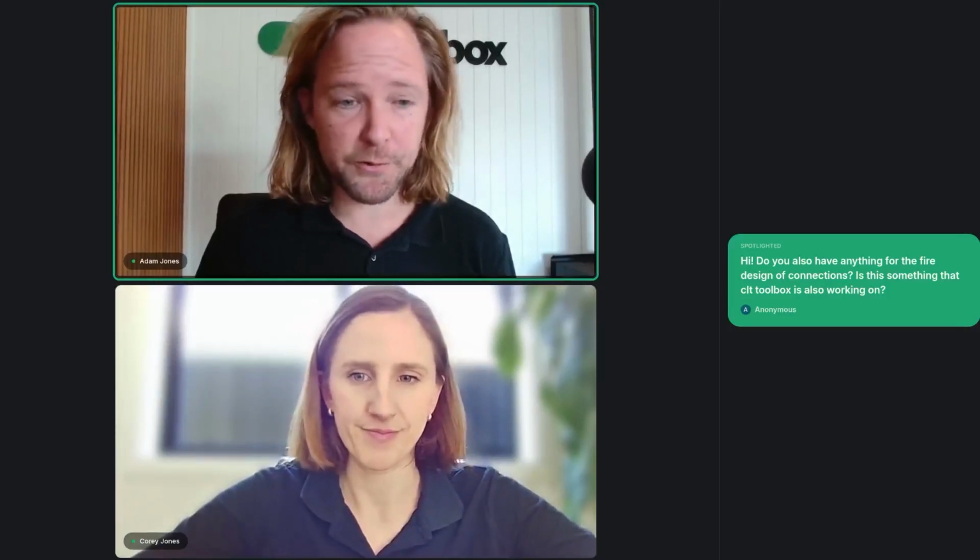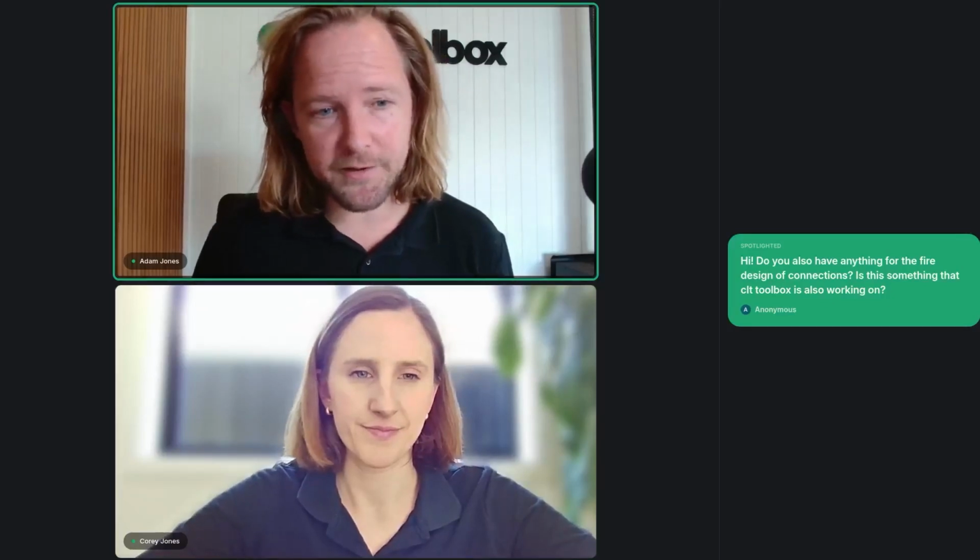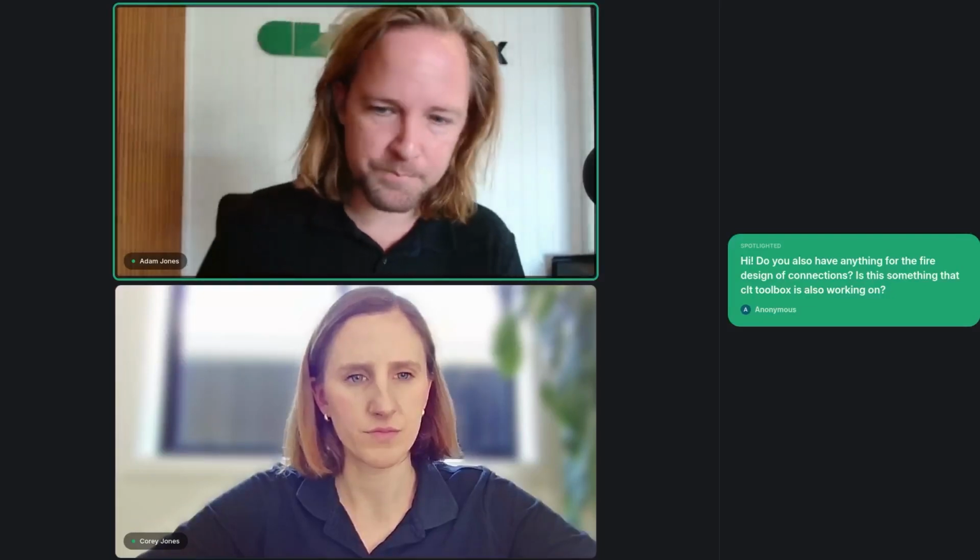Yeah, that's a great question. So we are right now building the char modules, like I showed you before, as modules. So you'll see them in the first step integrated into our connection details. For example, like a beam to column connection, by the end of the year you'll have charring around that. And then you'll be able to input a protection system around that to protect the gap or something like that. But yeah, that's coming. And then the other one over time is the exponential reduction method. We'd love input on how your actual screw reduces its strength in the fire scenario. So it's a great question.